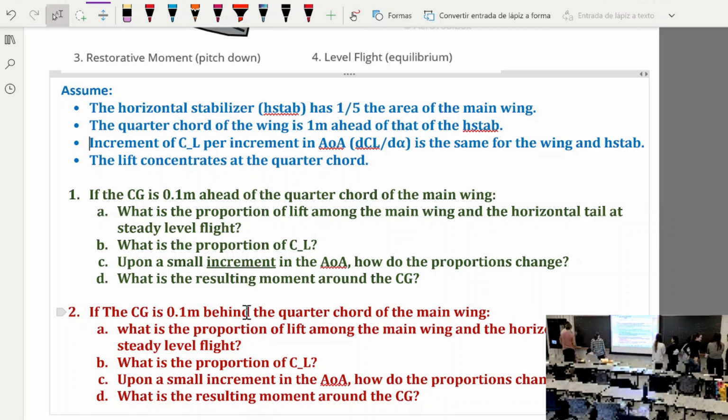Okay, so this is correct. How did you do this one again? We added a CL naught increment to both CL and CLH. And then we substituted the equation for CL into here, and then solved for the change, which is 6 over 11 CL naught. And then we just divided this expression by delta CL, which is just CL naught. So 6 over 11.